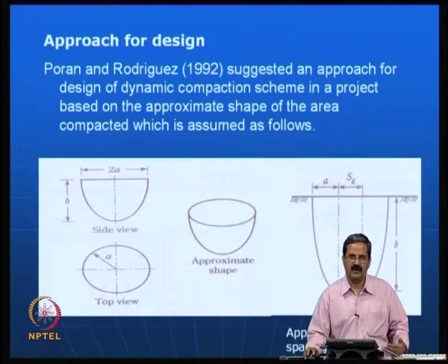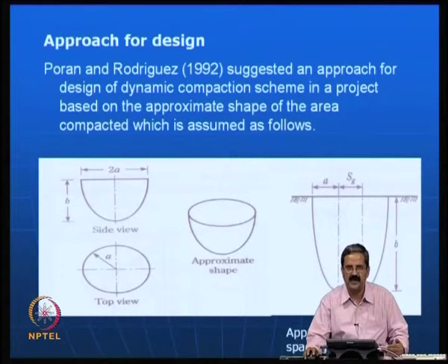Say for example, if you are trying sand drains, it could take a long time. But in the case of dynamic compaction, the area can be acquired quite fast. You must be able to design it properly, that is one thing, and then get the weights, get the tamping, get the proper contractor.